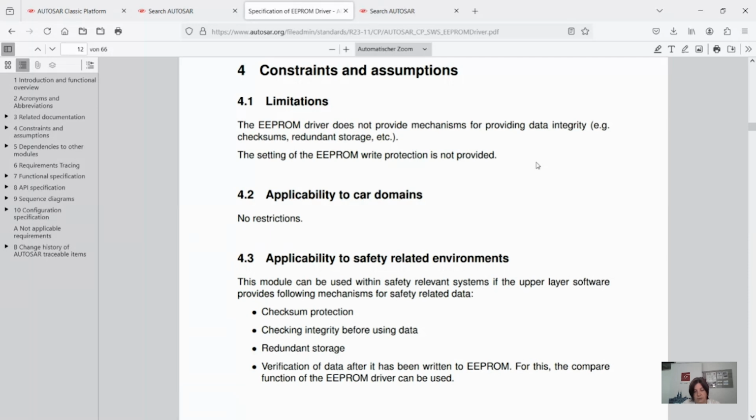And I can tell you, if you choose the recurrence of deleting and writing too often, then you can sit down and calculate and find out, okay, the ECU of whatever I'm doing in the vehicle will break at the customer side after 3 to 5 years, depending on how much they are driving. And this is something you don't want. So you really have to think, in terms of concepts, about how often you are erasing data there and writing new. I would say this is the most important thing to know about EEPROM. Yeah?